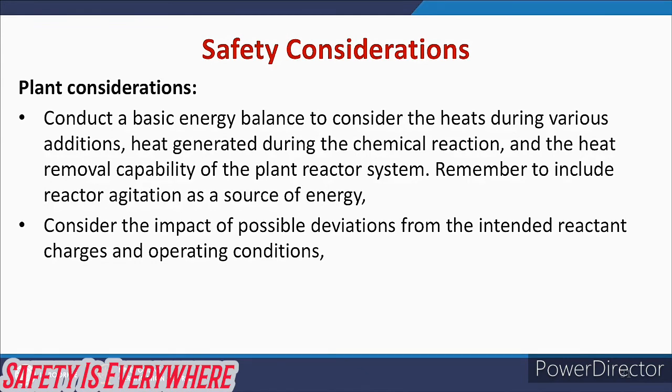Then the next phase is the plant consideration. Now, you need to conduct a basic energy balance to consider the heat during the various additions, heat generation during the chemical reaction and the heat removal capacity or capability of the plant reactor system. Now, remember to include the reactor agitation as a source of energy, because sometimes we may skip this important aspect while considering this plant consideration.